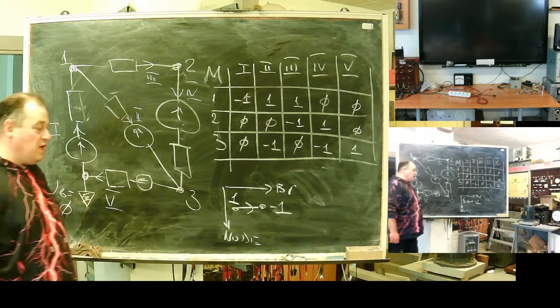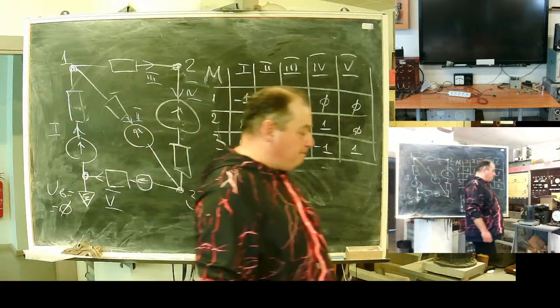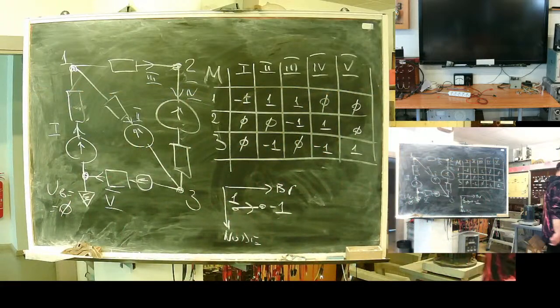It's ground for theoretical, abstract tasks, for faults, but for power flow tasks like this, it will not be ground, but a powerful station with voltage control. So it doesn't matter how many nodes we have, but we have to deduct the base one. Only one should be our reference point.